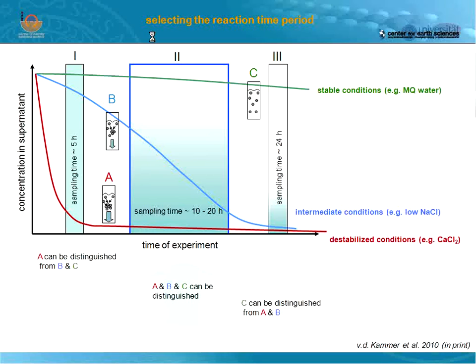We made a lot of tests to figure out the right way to do that. And in the end, we used simple turbidity tests for the titanium dioxide. For the gold, we are using ICP-MS because we are working at very low concentrations. The turbidity would not be sufficient. But using turbidity at a wavelength of 850 nanometers, so in the near infrared, works quite well. So it's a nephelometric turbidity.